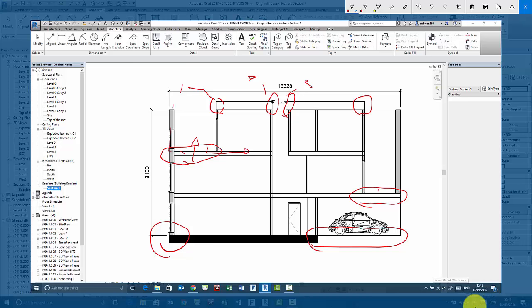because this is a classic problem. And there's only two ways to deal with it. You either lower the roof in such a way that you can put enough insulation in here, or you build up the floor outside here and fill it with insulation, and then you have to deal with how do you get from inside to outside and so on. So straight away you're starting to think about that stuff even at concept stage. And that's the kind of thing that maybe a professional client would be looking at as well.